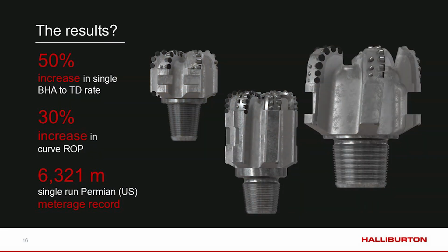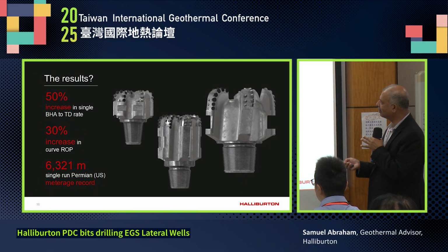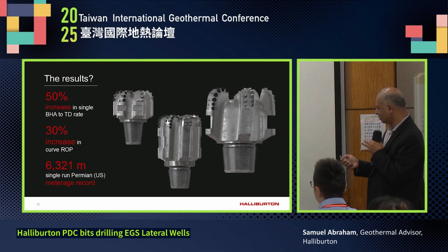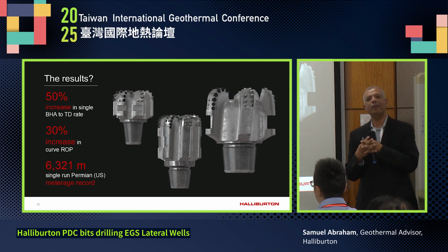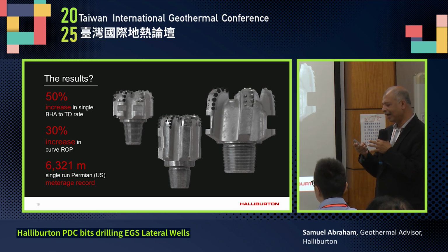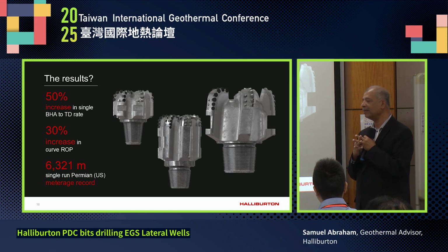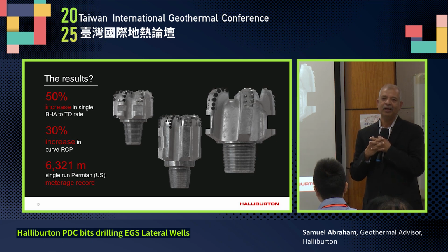And this one is talking for itself, so I won't. Sorry. So what are we finally looking at? Whenever we are making this bit selection, especially in the hypersteer, the type of bit that we have selected there, especially a PDC bit, not a tricone, what we have achieved is drilling one section with one bit, increasing the ROP by about 20 to 30%, and increasing the meterage. And most importantly, not leaving any cones in the hole.